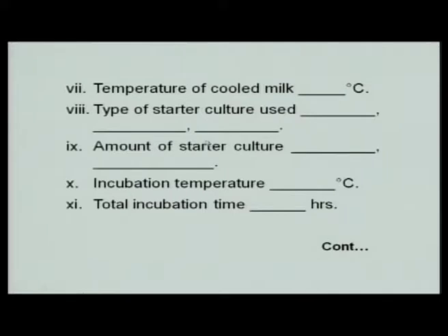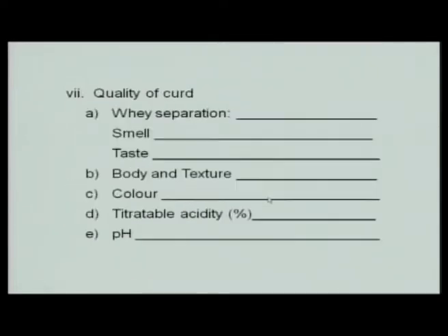Then the temperature of cooled milk, which depends on the culture; we cool it accordingly. Then the type of starter culture we use, we have to specify the amount of starter culture. Then we come to the incubation temperature and total incubation time. All these parameters depend upon which culture we are using and what the temperature is.